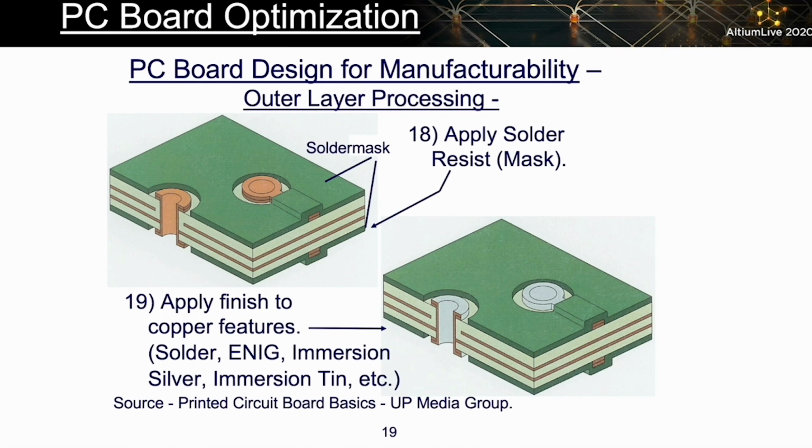And oh, by the way, I think I might have mentioned this talking about Happy's report card. Unless you need ENIG on the board because of needing really flat pads, you shouldn't be using it. It's one of the most expensive finishes there is. If you only have medium density surface mount components, meaning if you don't need really, really flat pads because of very fine pitch parts, you don't need ENIG. Use something like immersion tin or immersion silver, or maybe even an OSP finish, which is an organic finish. Only use ENIG if your assembler tells you, yes, you absolutely need it, because it's more expensive. It will add cost. Anyway, final finish, and then the board is completely done.